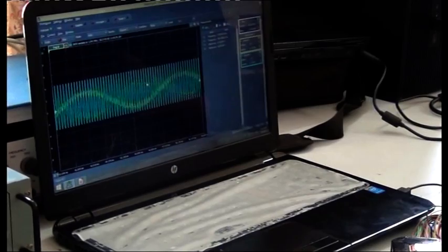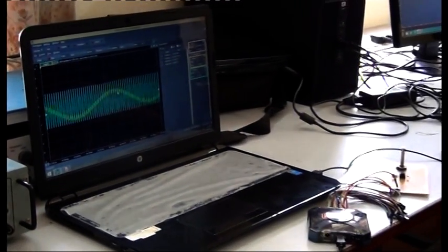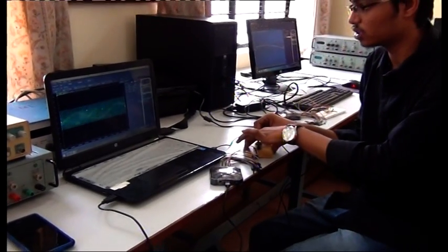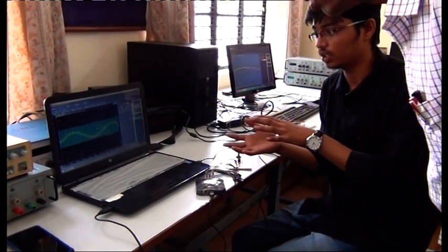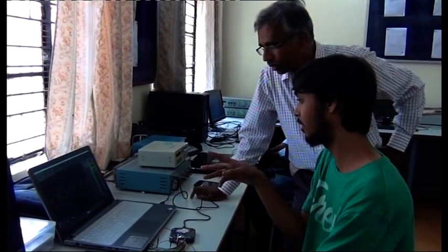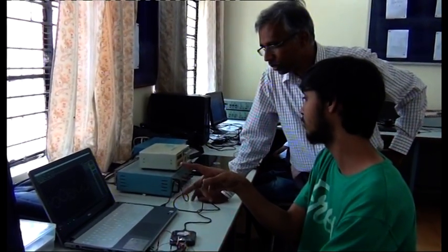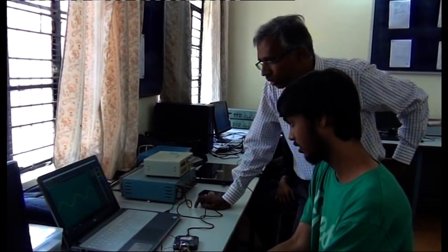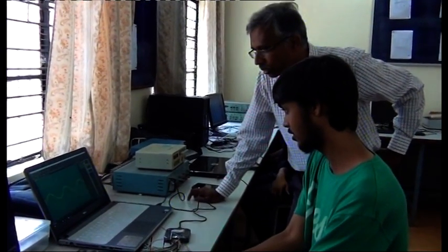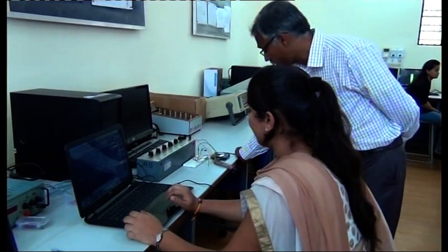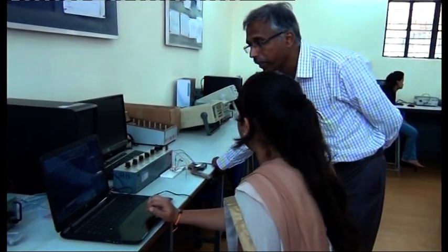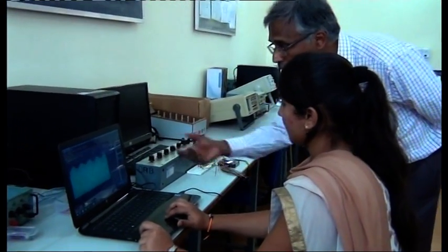On the imaginary axis. In the first case, as an amplifier, they are on the left side, on the left hand side of the plane. Now if we increase the gain too much, it is going to act as a square wave generator. From the left side of the plane, the poles will move on the imaginary axis towards the right side. Now it is on the imaginary axis. Gain is on the left hand side, so no need to measure.